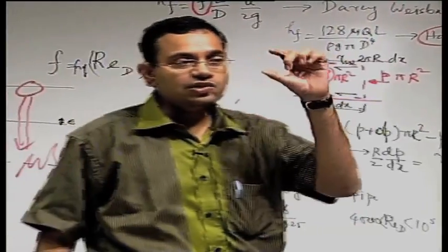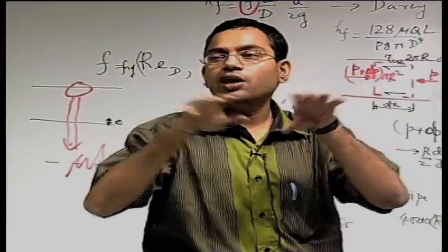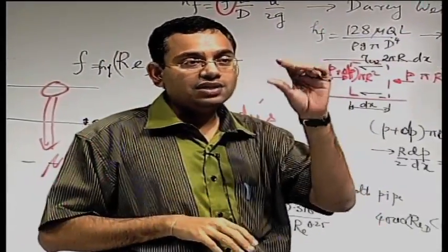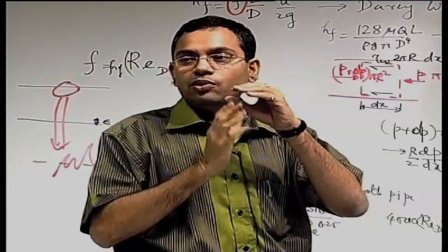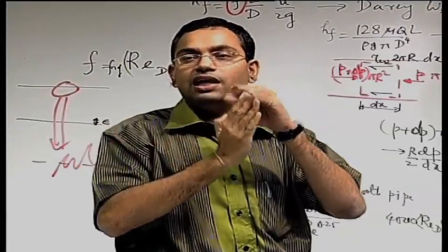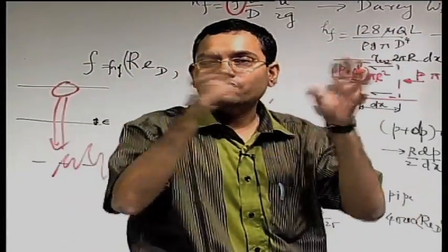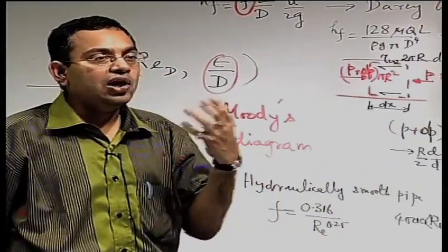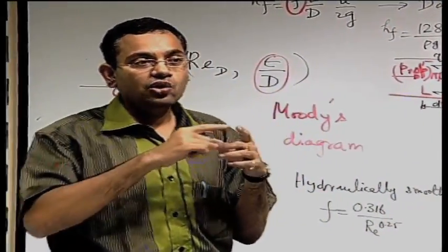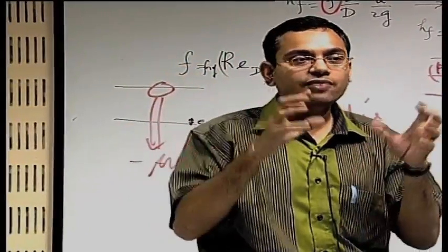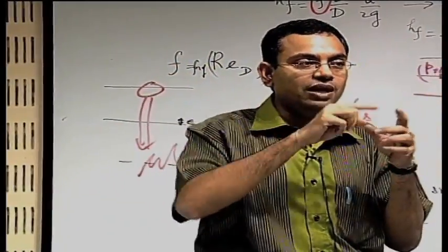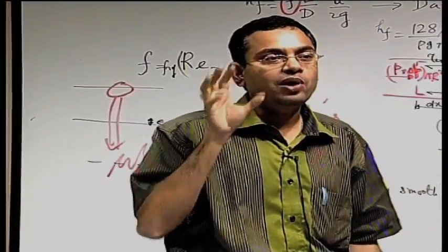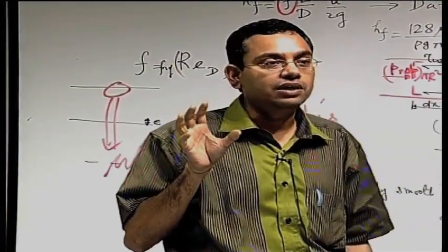If the viscous layer is quite thick, it cushions the wall roughness element, so it covers the entire wall roughness element. But if the viscous layer is thin, now the wall roughness elements protrude out and interact with the outer turbulent flow, and that will induce a lot of form drag or pressure drag, because local roughness elements are like flow past bluff bodies. So if you have local rough walls around which the fluid is flowing, it is flow past bluff bodies where the form drag or pressure drag becomes very important.